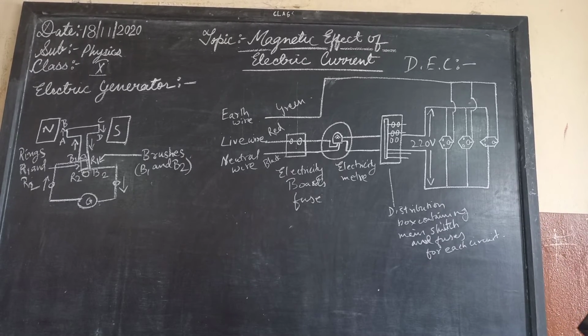We have already studied the principle and working of the fuse in the previous chapter. The fuse prevents damage to the appliances and the circuit due to overloading. Overloading can occur when the live wire and the neutral wire come in direct contact, when the insulation of the wire is damaged, or when there is a fault in the appliance. In such cases, the current abruptly increases and causes a short circuit. The electric fuse protects the circuit and appliances from possible damage by stopping the flow of unduly high electric current. Joule heating takes place in the fuse, it melts and breaks the circuit.